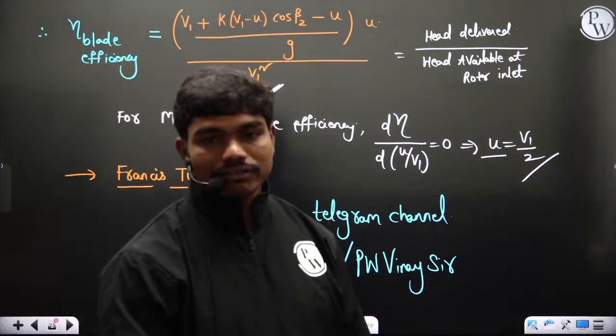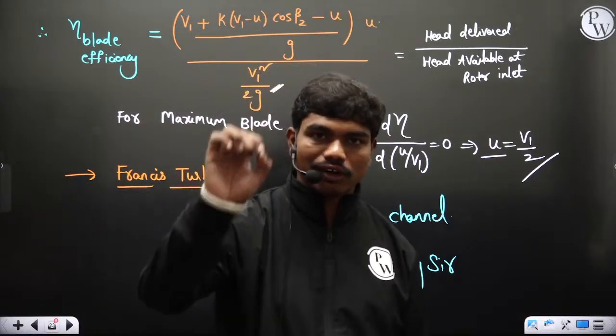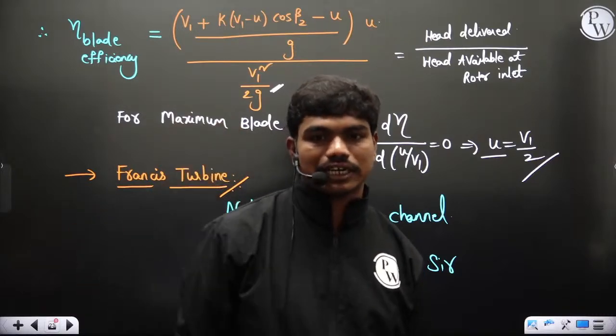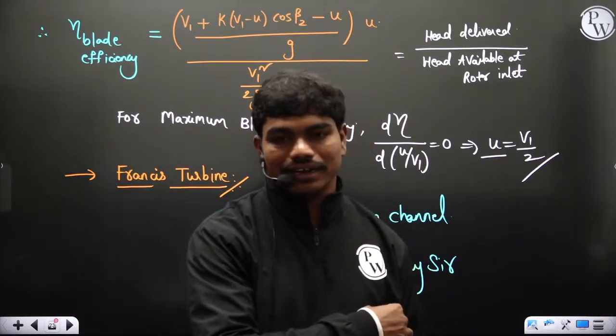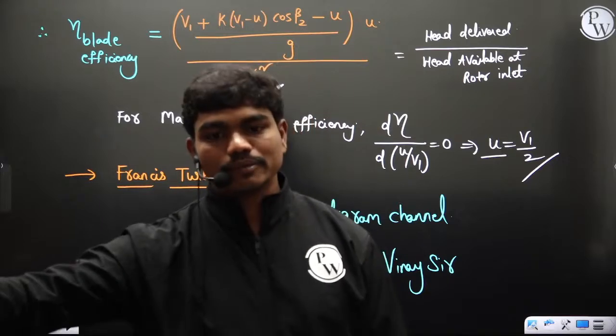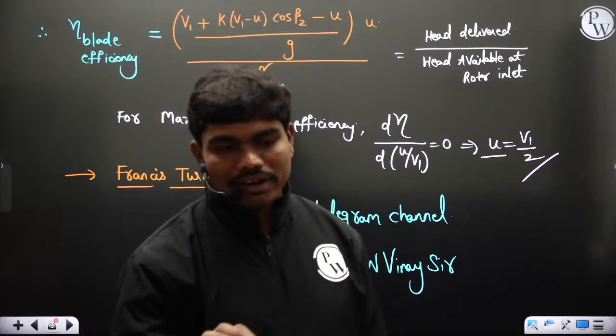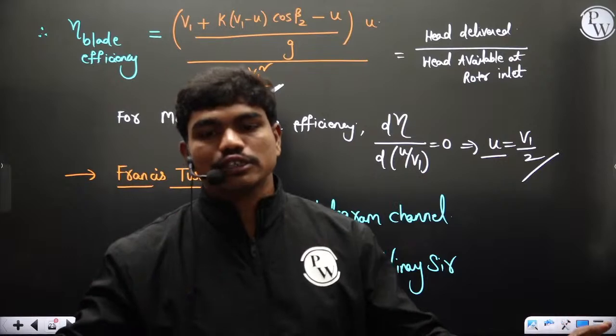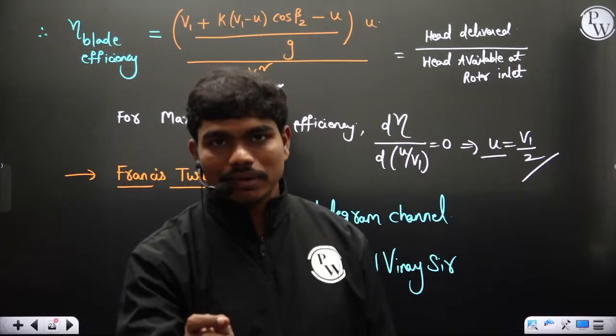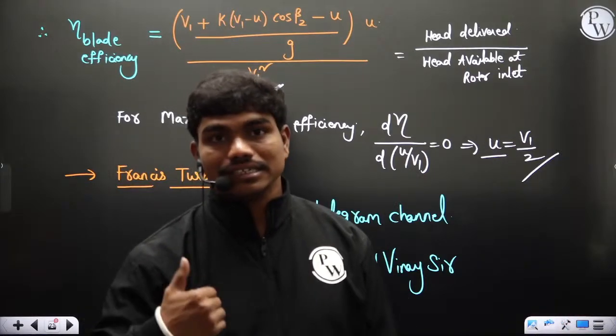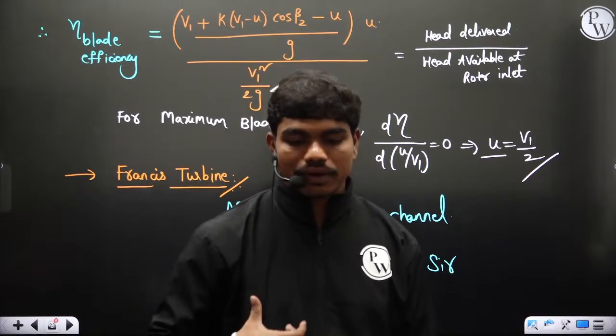Okay, you have certain logics. Everything you do, you have certain logic and certain physics developing that logic. It's not like since I like N over P so much, I take N over P by H power 5 by 4, nothing. You have to eliminate the diameter, meaning independent of the geometry of the machine, what speed the machine should operate at for generating 1 unit power. These are the important understandings that you should make when you're doing turbo machines.